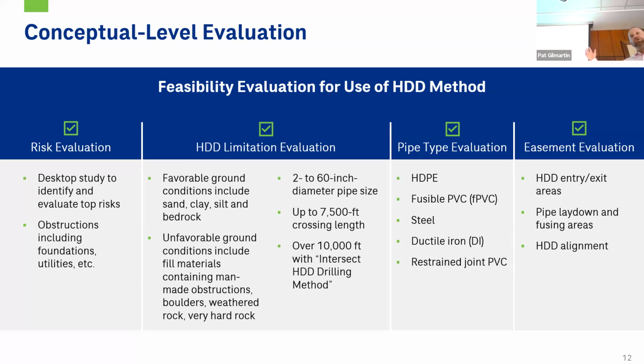And with those drills, you actually drill from either end and then you meet in the middle, and they have very advanced equipment to be able to have that sort of accuracy. Additionally, it allows you to have pipe pushers that actually help the drill rigs, because the forces are so great that an individual drill rig can't push the HDD in there.